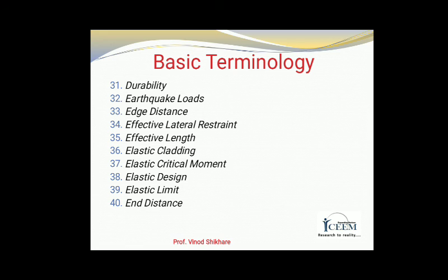Then elastic critical moment. The elastic moment which initiates lateral torsional buckling of a laterally unsupported beam. Then elastic design. Design which assumes elastic behavior of materials throughout the service load range in designing of any member or structure.